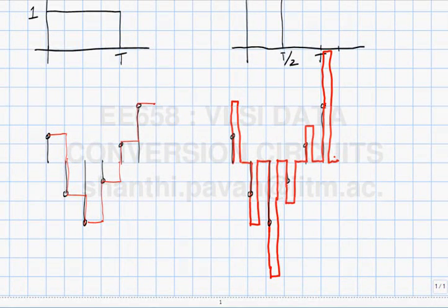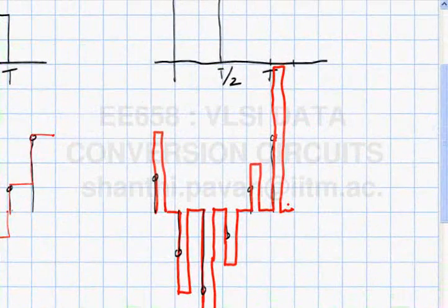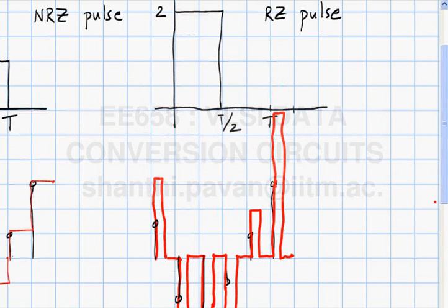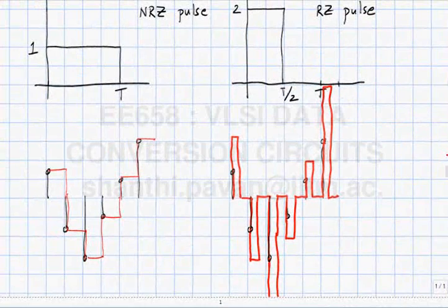Okay, so it has to do with practical implementation. So we have this NRZ pulse shape. In other words, we want to have a filter whose impulse response is this. So how will you implement it? Do you want to put an analog filter with this kind of impulse response? First of all, is an impulse response like this realizable? To get an analog filter of this form is impossible because there are sharp edges.